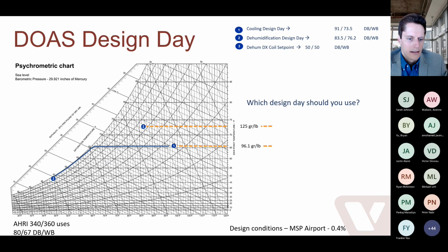Let's just take a look at the psychrometric process. If we cool down, let's just choose a compressor size. Let's say this is a 10-ton compressor, right? So we're going to cool down to about 50 degrees. And then our space is going to naturally heat back up based on the given loads in the space. We're going to sit at 75, 50% RH. So great. We're at a good set point. That humidity is in the right range. Great. So we'll call that a 10-ton system.